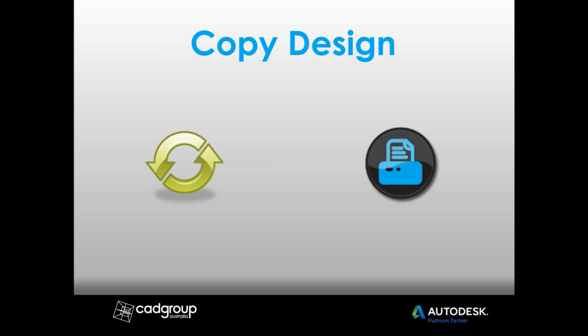Now, copy design will preserve all the relationships and will eliminate hours and hours of rework. For example, it'll take a part and the related drawing file, and it'll copy them and assign them new names. The new part and the new drawing file are fully associated to each other. The new dimensions and the new view layout from the original source document are preserved within the new drawing.